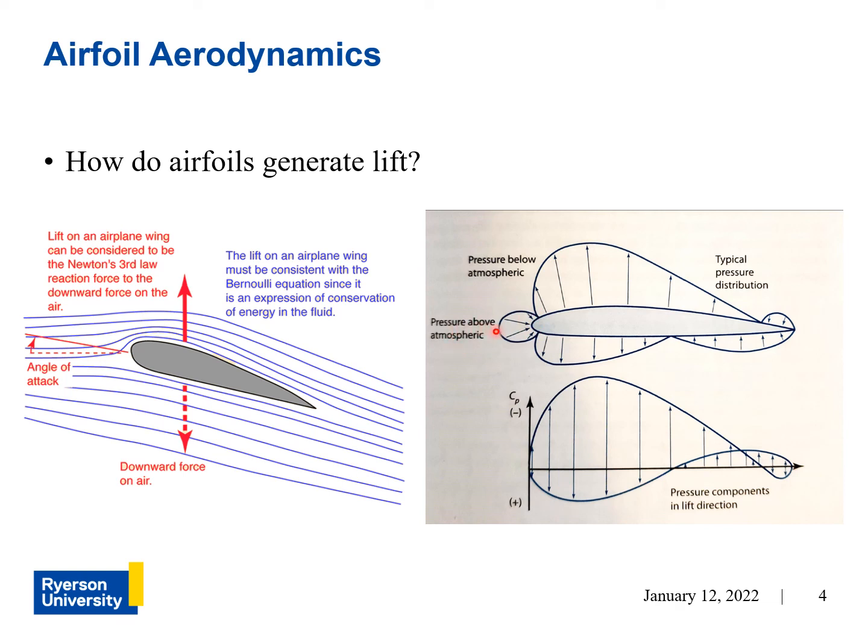And now as the air travels underneath the airfoil, according to this diagram, I suppose the air is traveling faster than ambient here in this region, because you can see that the arrows are moving away from the surface of the airfoil. And here at this point, the airflow is slower than the ambient flow.